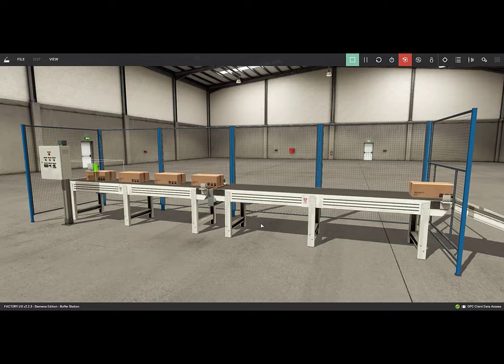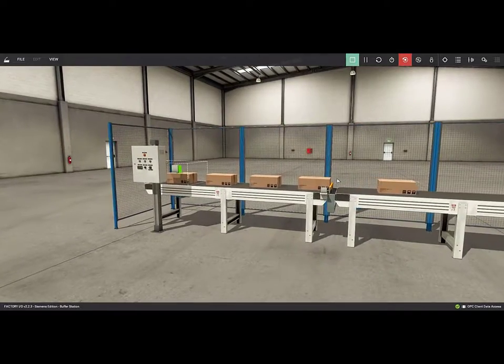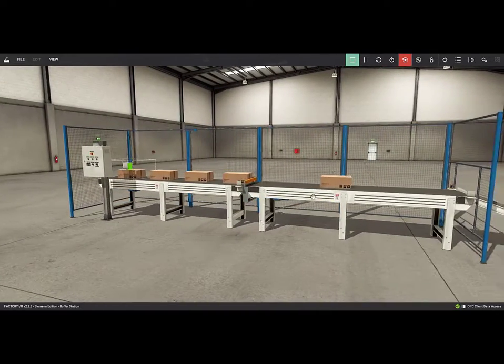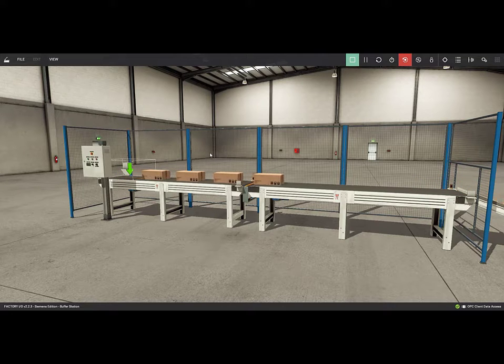While the box that passes through the second conveyor reaches the end, where it is detected by the at exit sensor, it simultaneously deactivates the stop blade, activates the first conveyor, and lets the next box pass. This process is repeated until the operator presses the stop button, which deactivates the actuators, stopping the entire process.